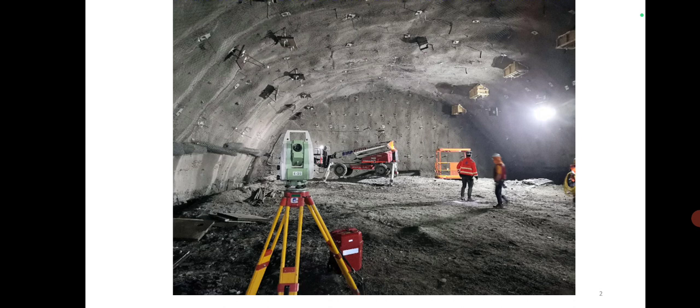That should be selected in such a way that unsafe conditions created due to the secondary structures, or due to groundwater conditions, etc., are avoided as far as possible. And when you select the excavation method, it should not disturb the overlying rocks or overlying soil.